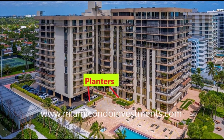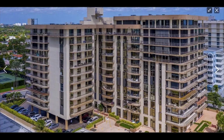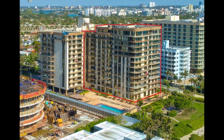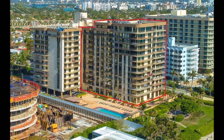And as Josh Porter states, the pool deck area had a safety factor of 1. There is no leeway for any deficiencies during construction in items like missing reinforcing steel or the inadequate spacing of the rebar or the insufficient design under the planters, and so on. And as Josh states, incredibly, the Champlain Tower stood for as long as it did with a factor of safety of 1 at the pool deck.